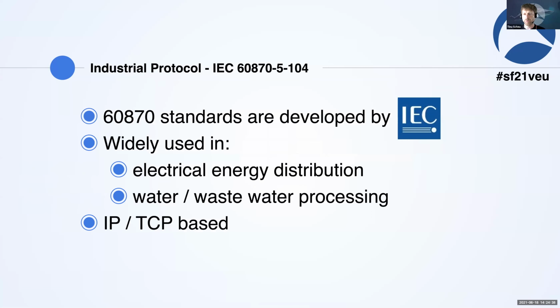Today I want to look at the industrial protocol IEC 60870-5-104. It's a very old protocol. It used to run over a serial 2-wire bus, and it was then ported into TCP/IP communication. This means that inside the TCP packet, you have other communication. This protocol, IEC 104, as I call it for short, also has keep-alive or checksum, basically the same as what you know from TCP, just encapsulated in the payload.